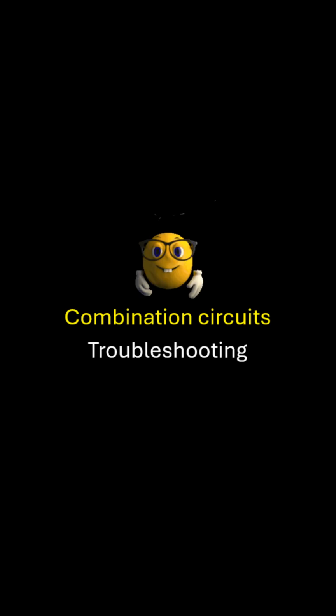8.3 Troubleshooting a combination circuit. Once the electrical concepts of combination circuits have been mastered, troubleshooting such a circuit is a relatively easy task. In most cases, taking voltage readings of individual components is the most convenient method to use. Look for an open or short circuit condition as indicated by a voltmeter.